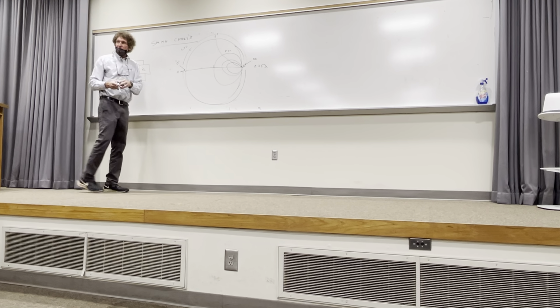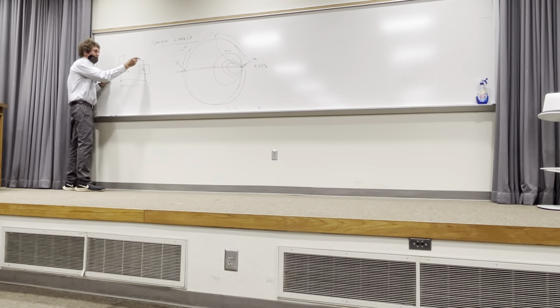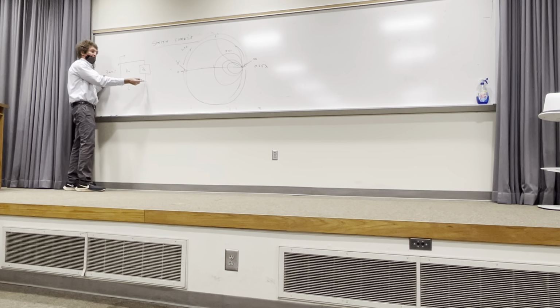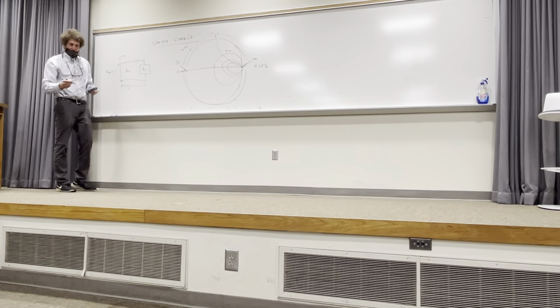So what that means is this. If I get a normalized impedance here, and I move a half wavelength away, it's the same impedance as it was here, or it would be ZL. So if it's ZL right here, if I move a half wavelength, it's ZL here. Y'all follow me in that, class? Every half wavelength it repeats itself. So this is going to be important.